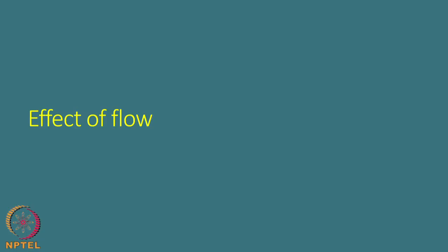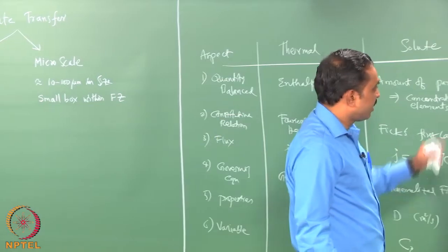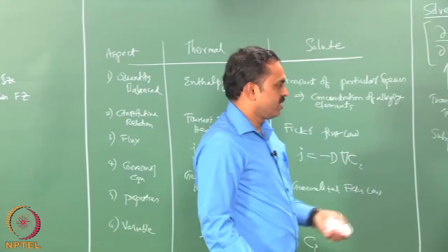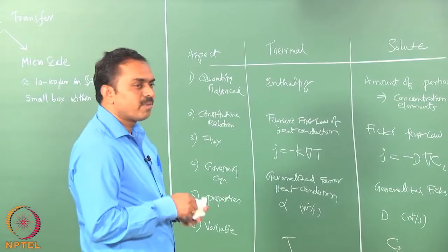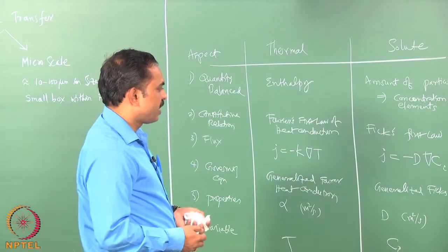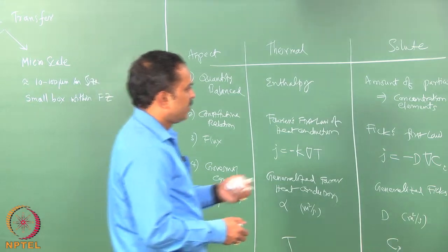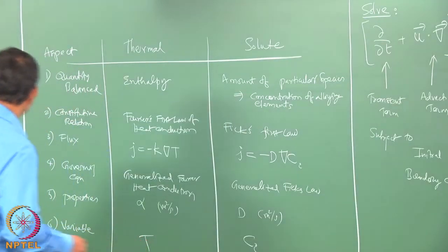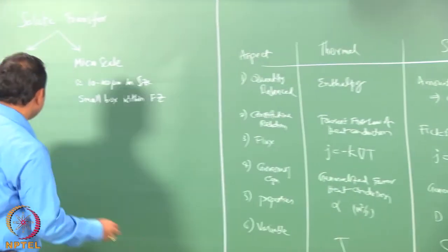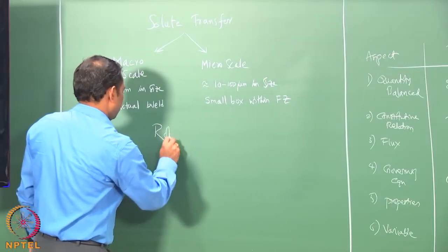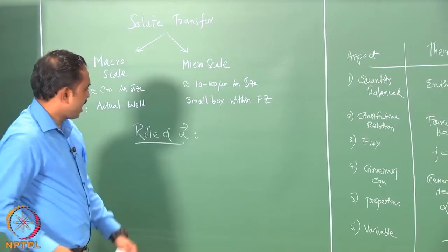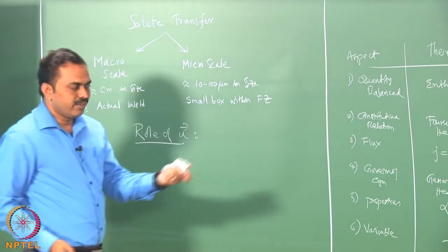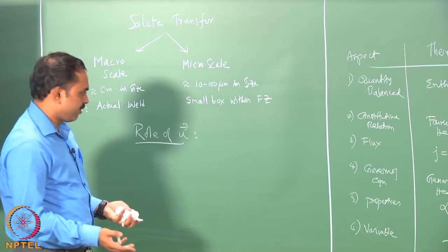Okay. So, one word about the flow and the reason why these kind of equations are not very popular in the welding literature, and why we normally ignore the solute transfer at the macro scale. I would just mention the role of viscosity, the velocity here. You could see that velocity in the weld pool is coming from 3 different driving forces.